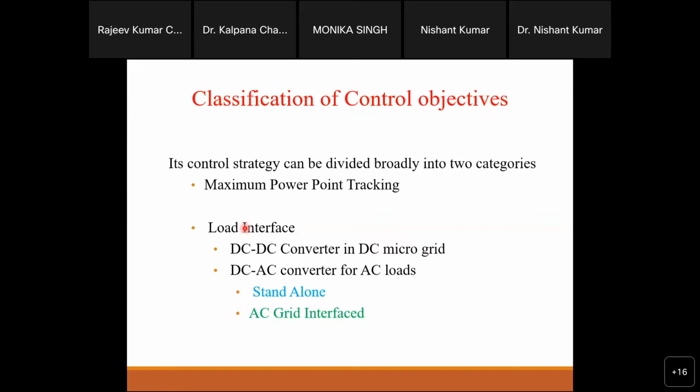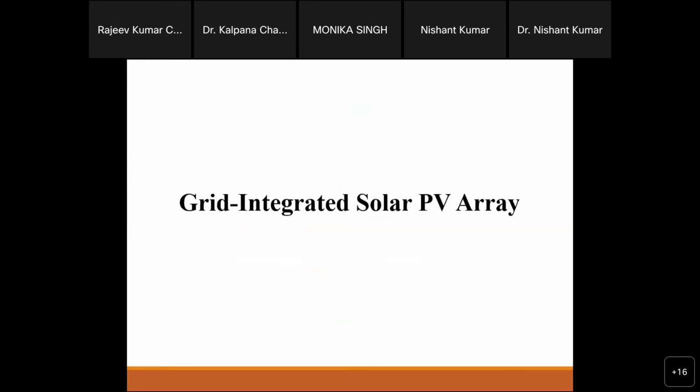But after that, on the power quality side, another norm is power quality issues. What is the level of power? What is the amount of power? Accordingly, we should follow the grid quality, or the power quality, or the current quality. For example, THD, total harmonic distortion, should be less than 5%. This is also a power quality norm for grid integration. So we should follow all those things, and who will fulfill these objectives? Our control will fulfill them. These are the basic norms when we are going to integrate with the system. Okay.